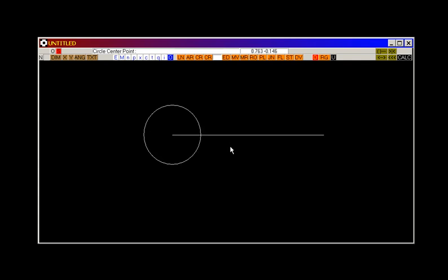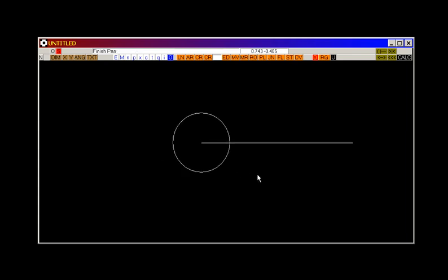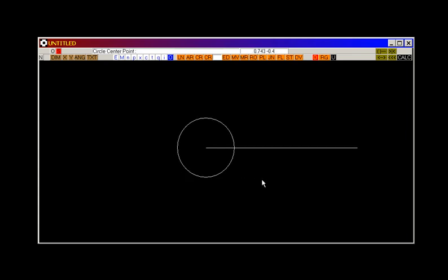All right, and now I want to put a flat on the bottom. One thing you should always keep in mind is when you're designing tools for punch or burn, that if that tool is symmetrical, it should be symmetrical about the y-axis. In other words, if there was a line going through here, it would be the same on either side. All right, so I want to put a flat down at the bottom here.